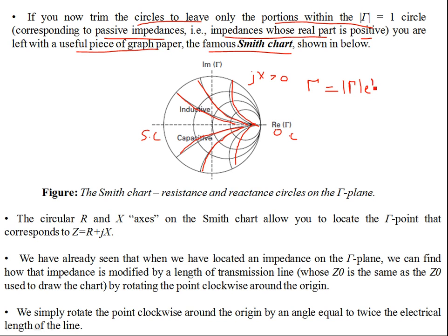Theta is the phase of the reflection coefficient, because your load can be complex, with a non-zero imaginary part. If you consider gamma at z equal to 0, that's the case. And if ZL is complex, that means gamma is complex.